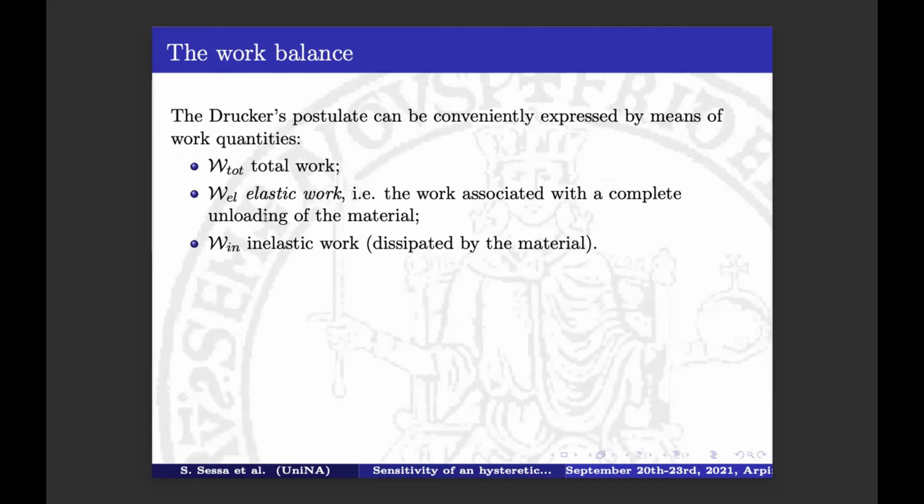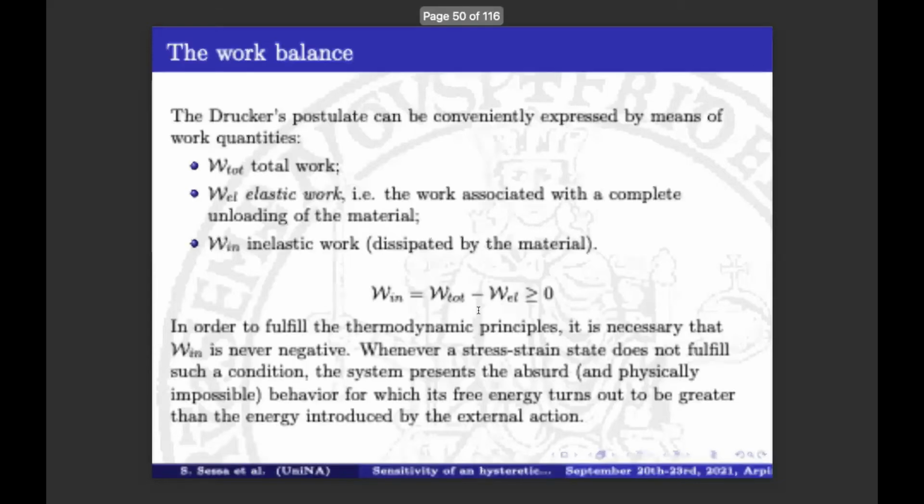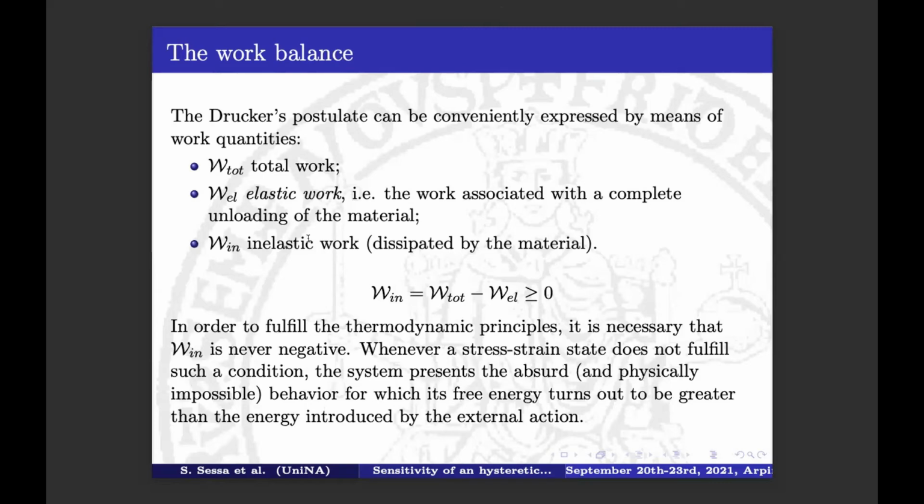I will call it elastic just by analogy with the classical theory, but actually this is not an elastic behavior. This is the work that is associated with the unloading, a generic unloading of the material, and the inelastic work, which is the one dissipated by the material, is the difference between the first two terms. In order to fulfill Drucker's postulate, we must enforce this condition.